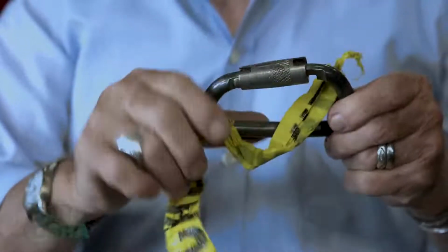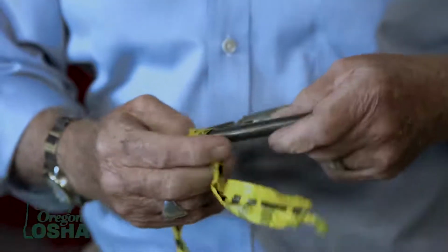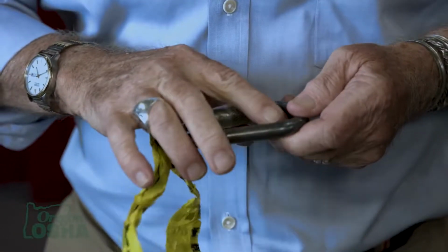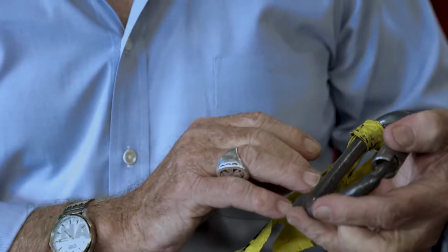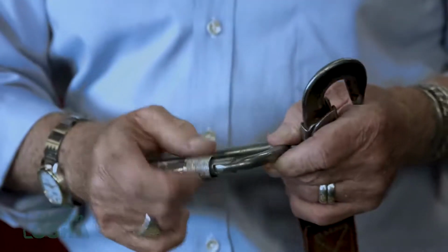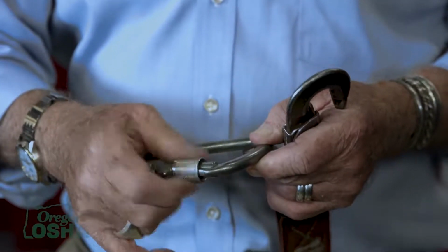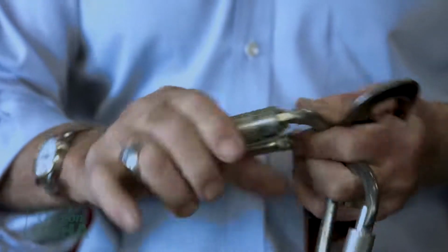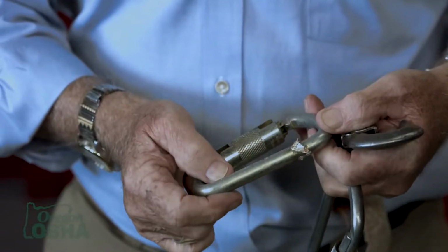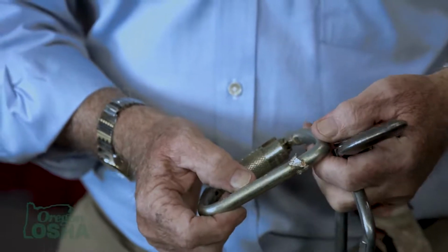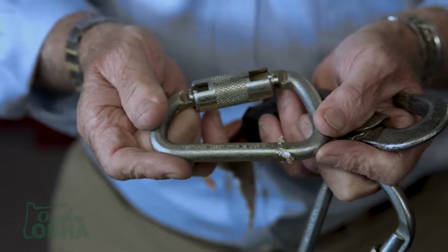Check your carabiners, need to open and close. Read what's on them. Make sure that you understand what's being talked about. It's talking right here about kilonewtons, and it takes 22.2 kilonewtons to be 5,000 pounds. Legitimate carabiner, it requires two separate actions. You look for a fall protection program, something that opens and closes automatically, not something you have to screw shut. But you check them to make sure they close. You read the labels and make sure they're rated. Legitimate ones will tell you they're rated to ANSI Z359, and they will give you the strength requirements stamped right on the component.